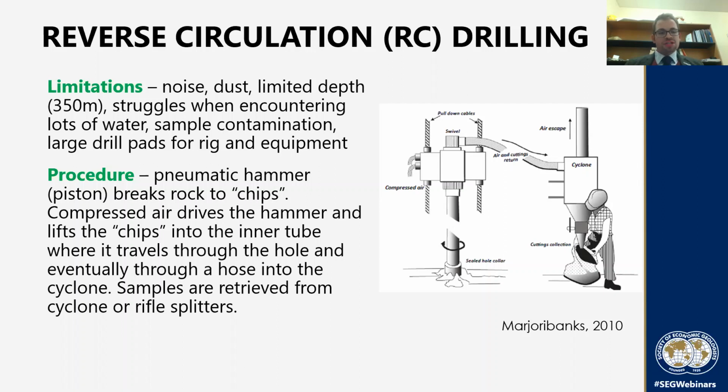RC drilling also has quite a limited depth. I myself have seen drill rigs drilling down to 350 meters in ideal conditions, but that really depends on the groundwater level situation. The technique will struggle very quickly if you have a high groundwater pressure, and that could lead to sample contamination, which I will discuss a bit later on.